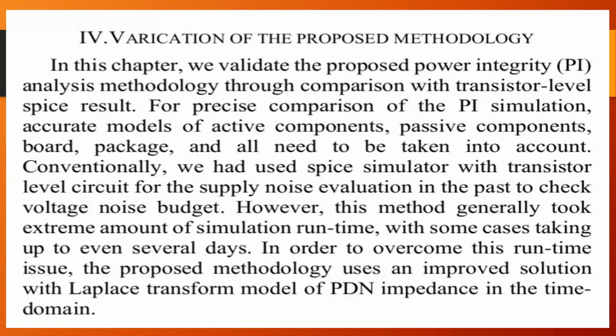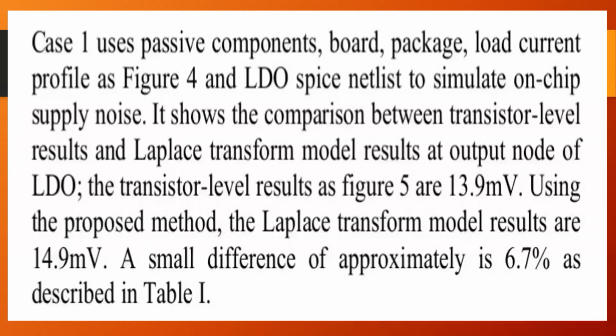Conventionally, we used a SPICE simulator with transistor level circuit for the supply noise evaluation in the past to check the voltage noise budget. However, this method generally took an extreme amount of simulation runtime, with some cases taking up to even several days. In order to overcome this runtime issue, the proposed methodology uses an improved solution with Laplace transform model of PDN impedance in the time domain.